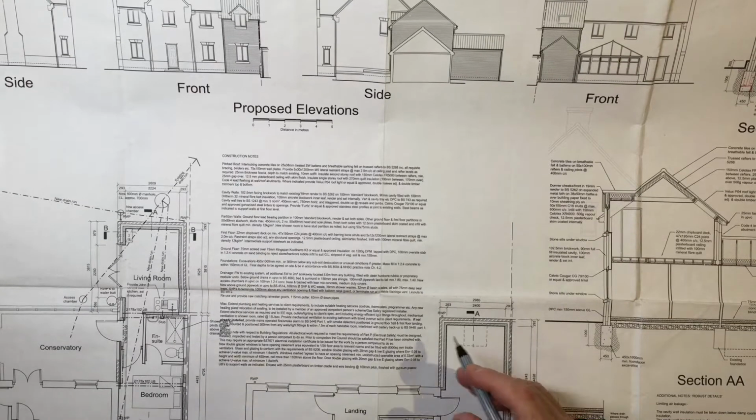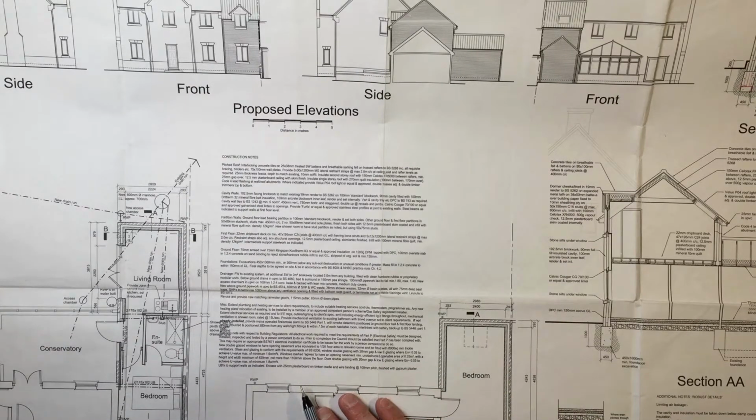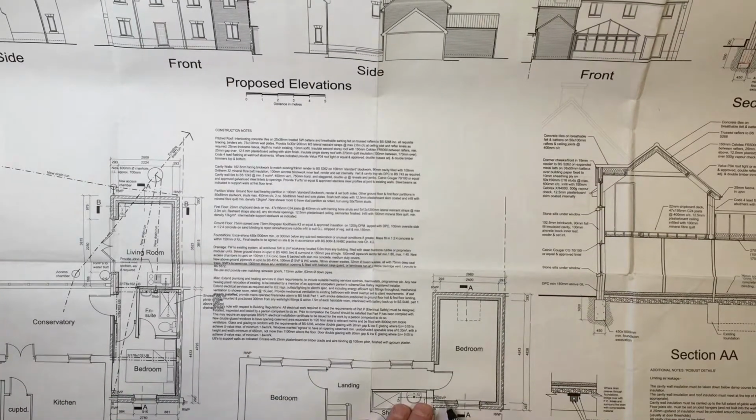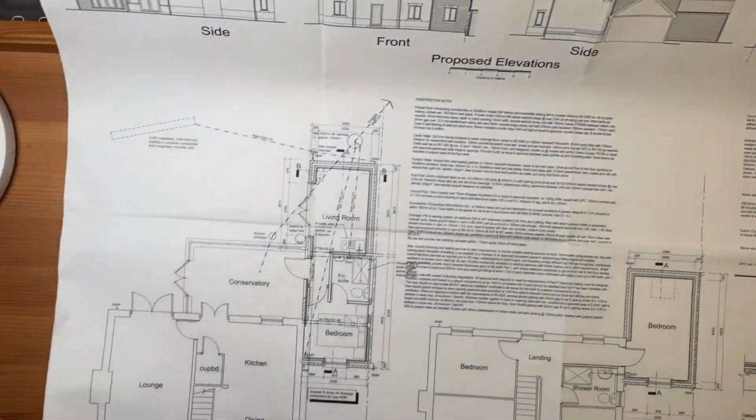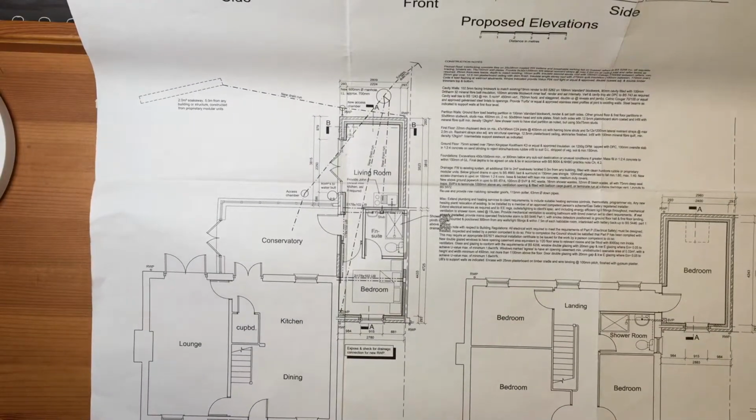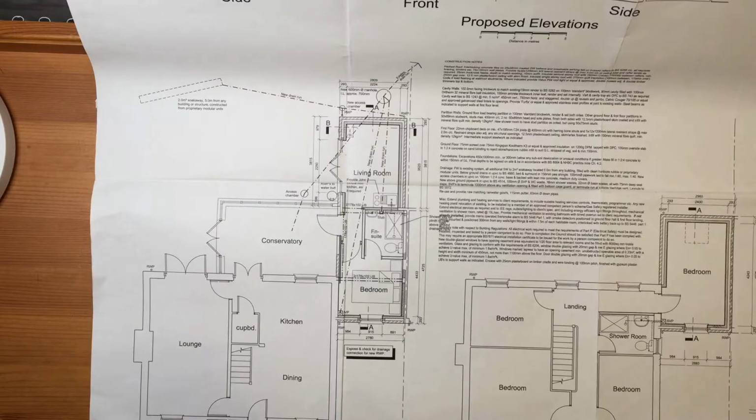Any other questions? So what are all the little words like SVP? Point to them. Oh, okay. This is sewage vent pipe, or foul water vent pipe. That's the venting to allow the air to enter the sewer, so you don't get what they call sort of blowback or suction when something's been flushed down the toilet or a shower's been running. So that's a vent pipe. What about a WC? Point to it, Jake. Where's WC? Oh yes, water closet. So WC is water closet.